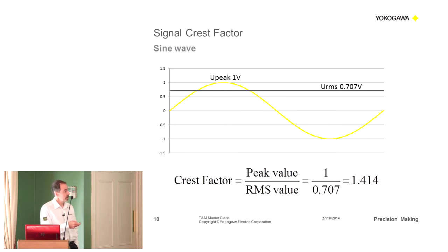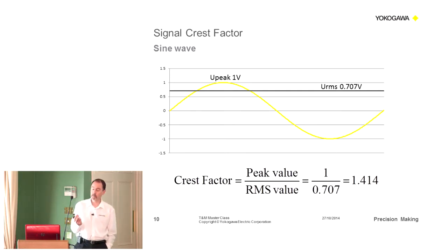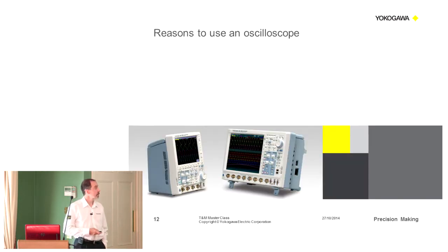So when you've got an oscilloscope type product, which of course is fundamentally defined by peak measurement ranges, if you've got high crest factors, your actual measuring portion, irrespective of whether you have high resolution or not, can be quite small. So that's where you definitely need as high resolution as you can get. In practice, you can get crest factors of 180 or even up to 300 in actual fact.